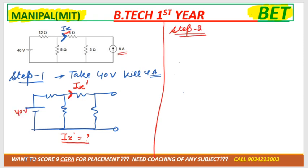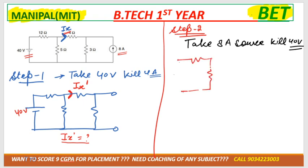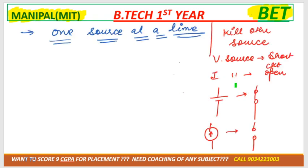First tell me. See, in the step number 2, we need to take 8 ampere source and we need to kill 40 volt. So now tell me, 40 volt must be short circuit or open circuit? If we want to kill 40 volt source, then that must be open circuit. No, it has to be short circuit. See, I told you voltage source means short circuit, current source means open circuit.